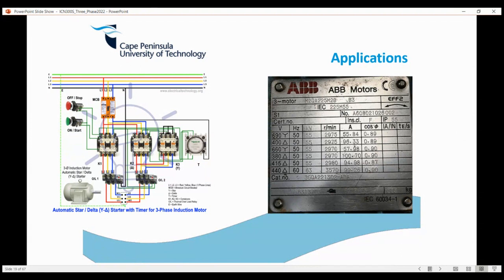That's what it means. What it means in this case, if you run the motor at a 50 hertz supply and 400 on delta, it will draw so much current at that power factor, and this is questionable, and it will still give you 55 kilowatts of power. So there's a few varieties. I can connect the motors. Obviously, there's a terminal box which is over there. You can connect it with star and delta, and depending on the supply and the connection and frequency, you'll get a different thing. You can see if you have 440 delta, 60 hertz, 63 kilowatts.